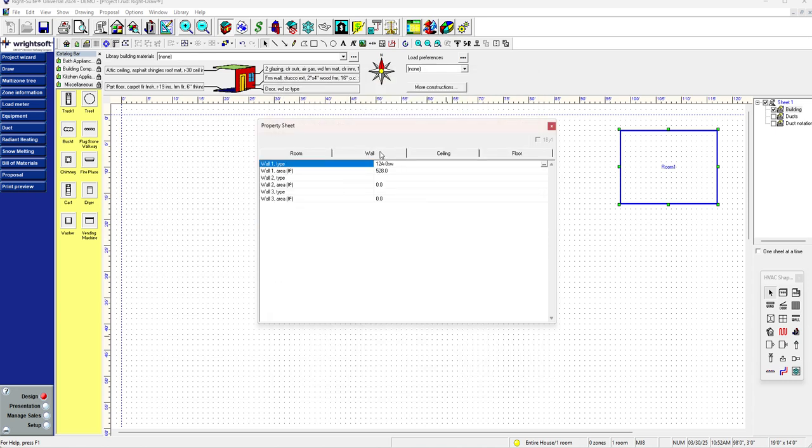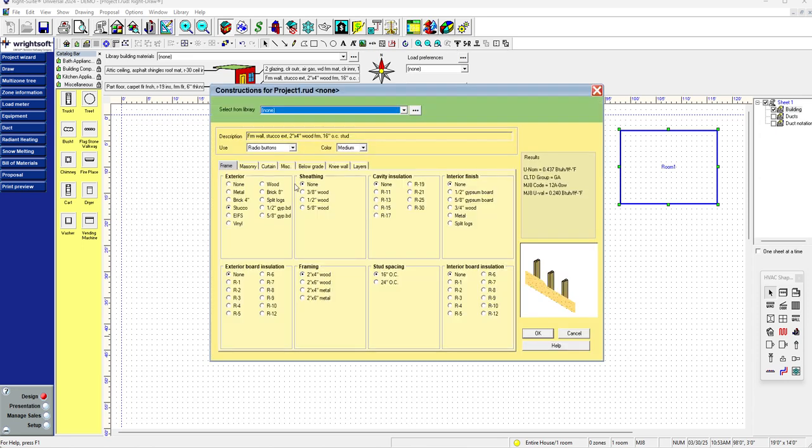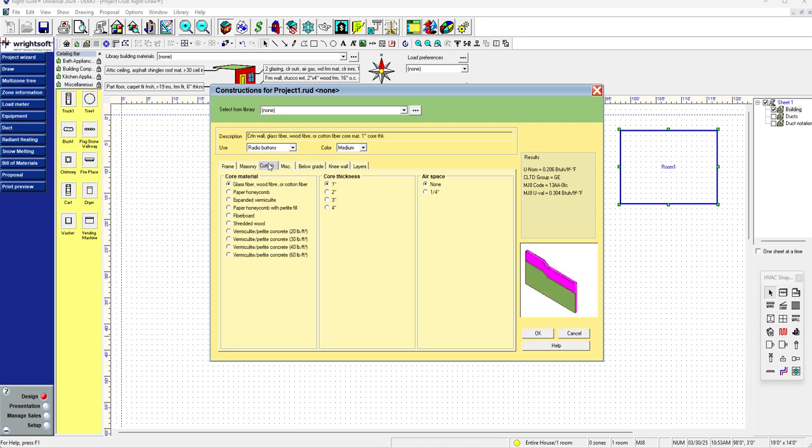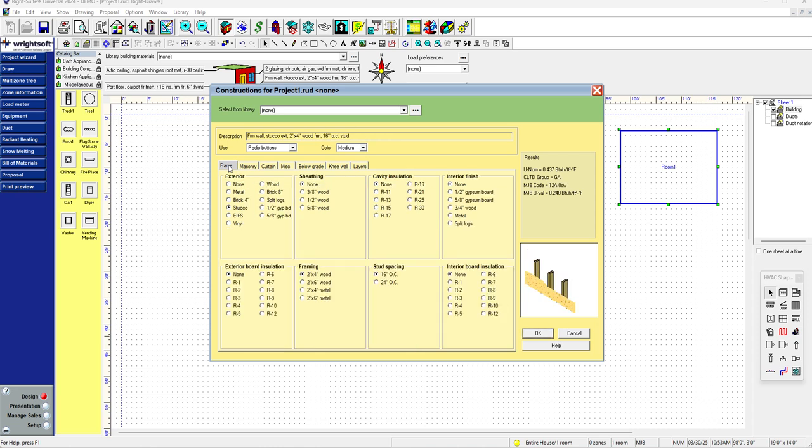All right, now for this particular room, we are going to specify the type of wall. We're going to click over here on these three dots. It'll bring up this pop-up. So in the United States, it's most common to have a frame home, so it's 2x6s or 2x4s, okay? Sometimes you might hear people say a block home, maybe like cinder blocks or concrete blocks. That would be a masonry home. There could be other types, but most common for sure is the frame type.